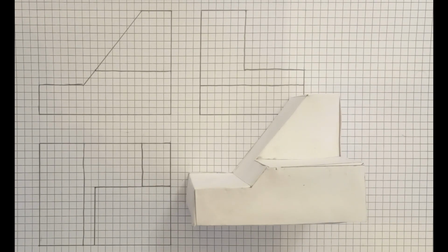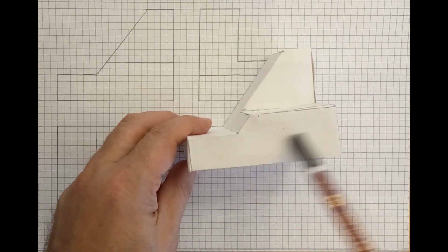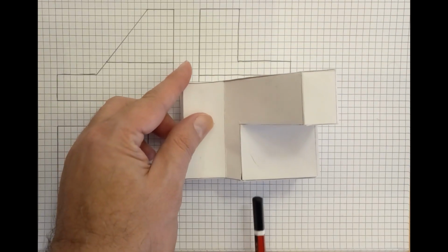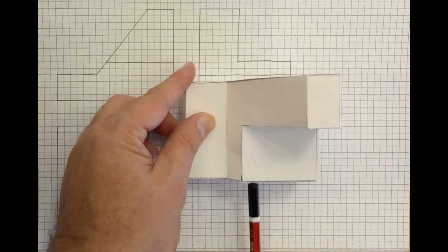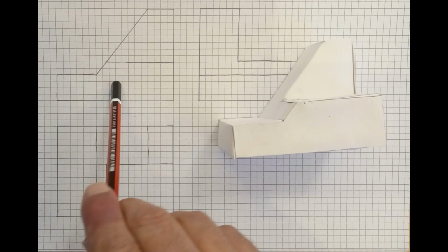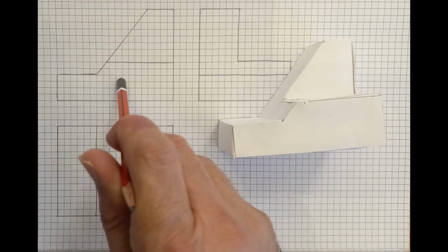While if this surface is inclined, it will appear in two views as a shape with approximately the same shape but different dimension, and in the third view it will be a line. So if we apply this here, we have this surface. This surface is vertical, so when I am looking at the part from the front view, my side is perpendicular, so I will see it as a true shape with true dimension in the front view, while in the side view and the top view, it will appear as a line.